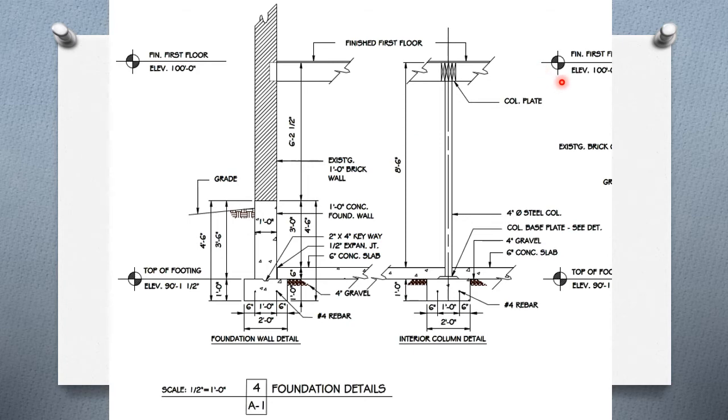Notice here is a survey marker. And again, this is an indication of the legends and symbols that may sometimes be used in one situation and used differently in another situation. Sometimes these are used to indicate where a soil boring is located. So you always have to use a little common sense and determine what your drawing is trying to tell you.